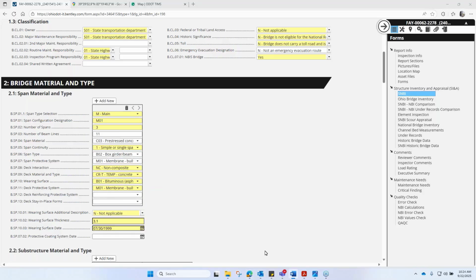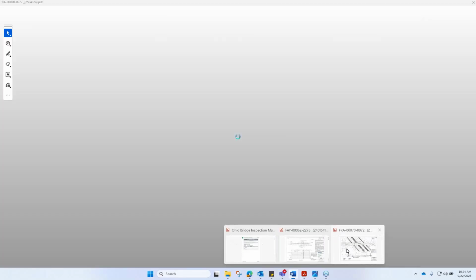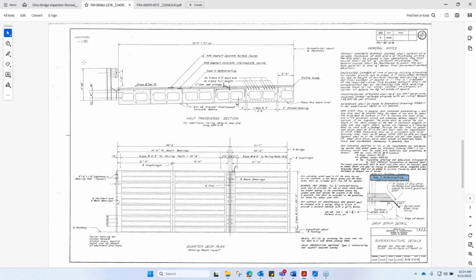We are going to, again, use the predominant coating, right? So we want to be neglecting when our fascia girders are either sealed or painted. Typically you'll see those on plans, right? You'll have kind of like a little line coming like this and be like, we've sealed this with epoxy urethane, or we've painted the fascia girders, but not the inside girders of weather and steel bridges. So we want to use predominant type in cases like that.